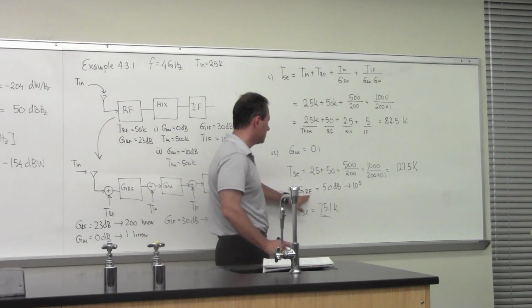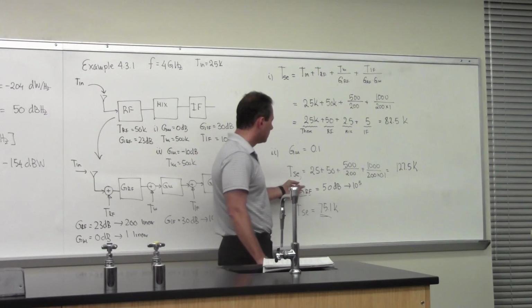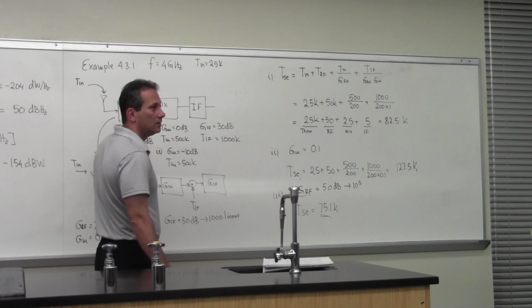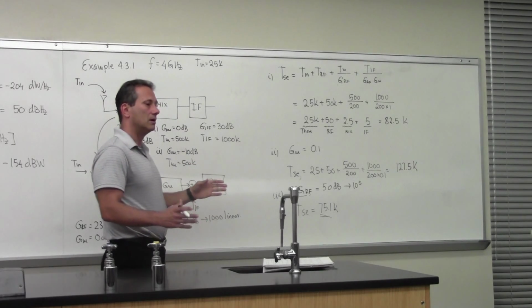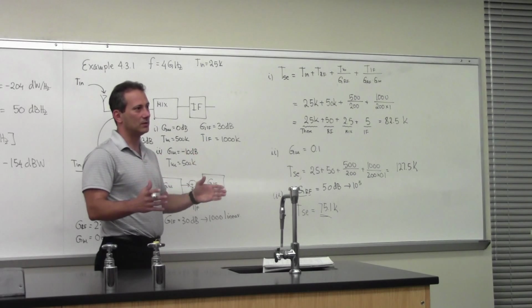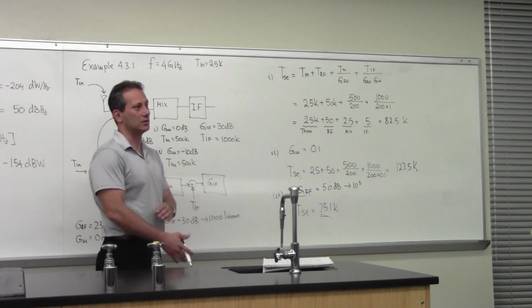But what happens is, you know that very well. This number here, the gain G of your antenna, and the noise figure of this stage limit your signal to noise ratio. In a given bandwidth, if I give you the bandwidth and the signal to noise ratio limit, that tells you the data rate you can achieve.